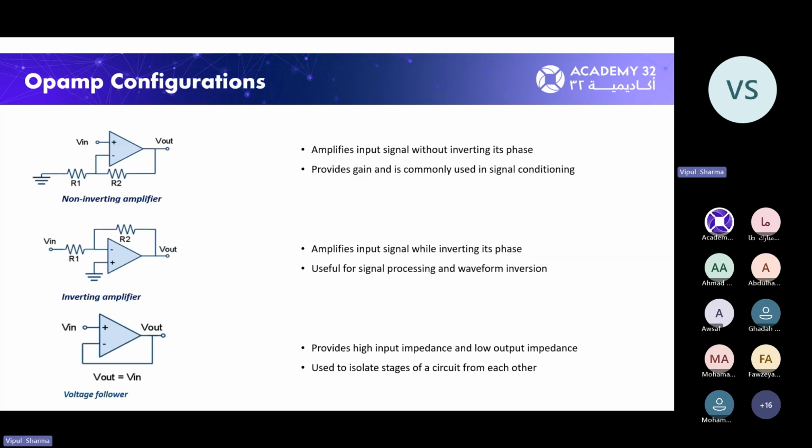So when you put this op-amp in feedback, this is how it looks. These are some basic configurations. I have included them here just to show you an example. If you want a non-inverting gain, where your input signal is amplified by, let us say, a gain of 3 dB, 6 dB, 9 dB, or maybe 20 dB, you can use it in this configuration, and you can change the gain by switching the values of these feedback resistors. Similarly, for inverting configuration, the input signal needs to be applied to the input terminal through this R1 resistor, and again the gain can be changed by changing the ratio of these values, that is minus R2 by R1. And if you want to use a buffer, it has a buffer.